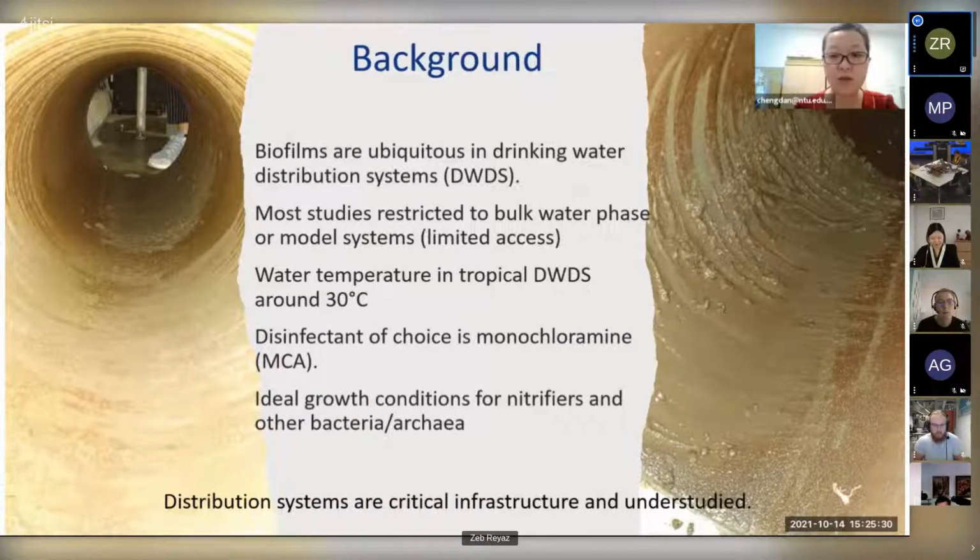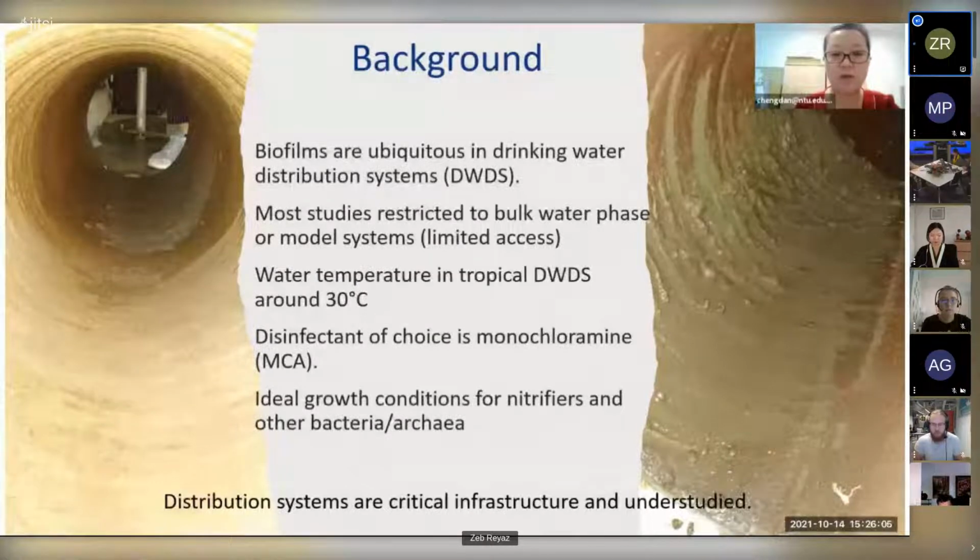Such stagnation creates ideal growth conditions for waterborne bacteria, associated with the decay of the secondary disinfectant in the chloramine system. The influence that stagnation can have on microbial communities of the built environment has been previously studied from household purifiers, plumbing systems for up to 5 to 6 days of stagnation, drinking water networks, flushing events, or fire hydrants by various groups. The impact of biofilm on the bulk water due to extended stagnation from national or regional lockdown remains unknown.